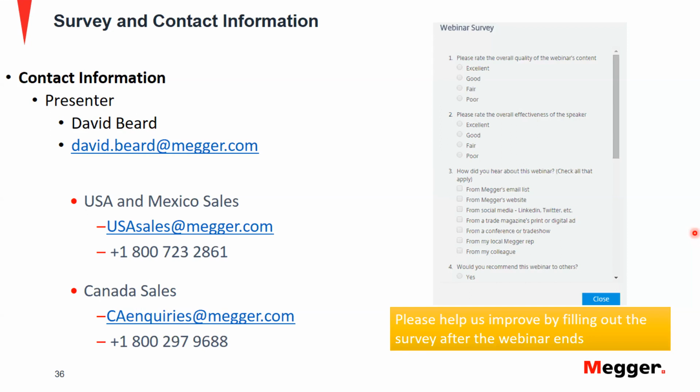Oh, thank you. Yeah. So yes, we can absolutely test breaker trip unit with the relay test set. We have a feature of recording time on our home screen, so anybody can use a pre-fault to fault home screen, provide nominal values on pre-fault, and then pick up values for the breaker trip on the fault state. And all they need is a way to connect to the binary input of the test set.